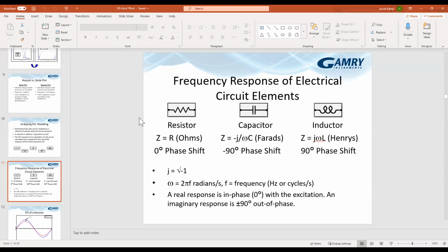So if you're making a measurement of EIS and you're monitoring the EIS and then you add an inhibitor, you actually shift the open circuit potential. So there's a lot of things that happen. So a corrosion system with an inhibitor getting added is a very complex environment. Monitor the open circuit, make sure that you're measuring open circuit in between additions and watching how things are shifting, and make sure that open circuit has stabilized before you start doing your impedance measurement if you're doing inhibitor analysis. Okay, thank you.